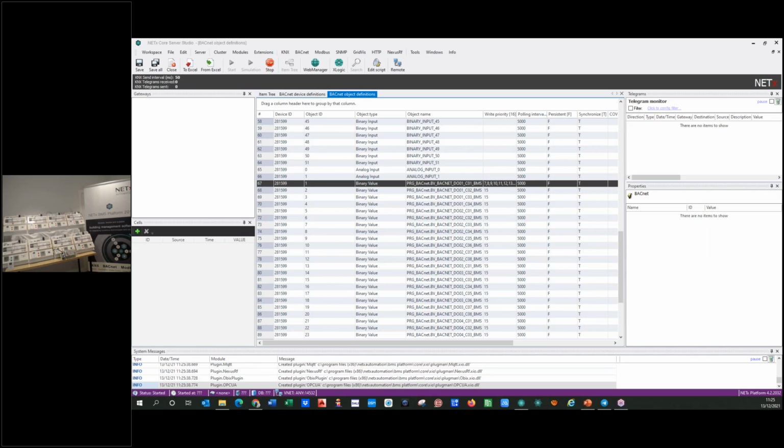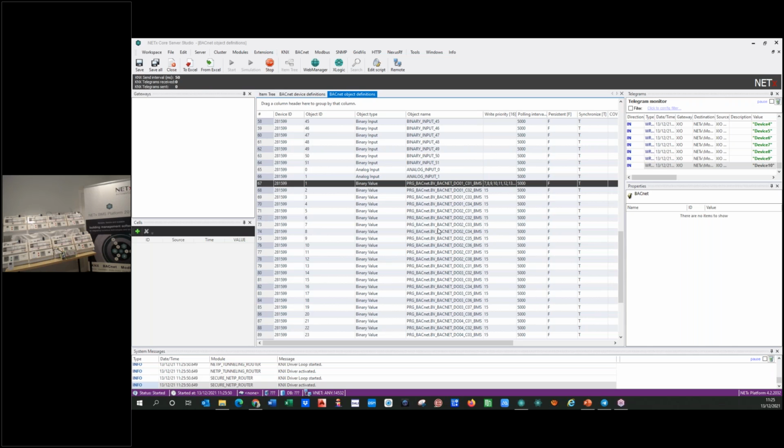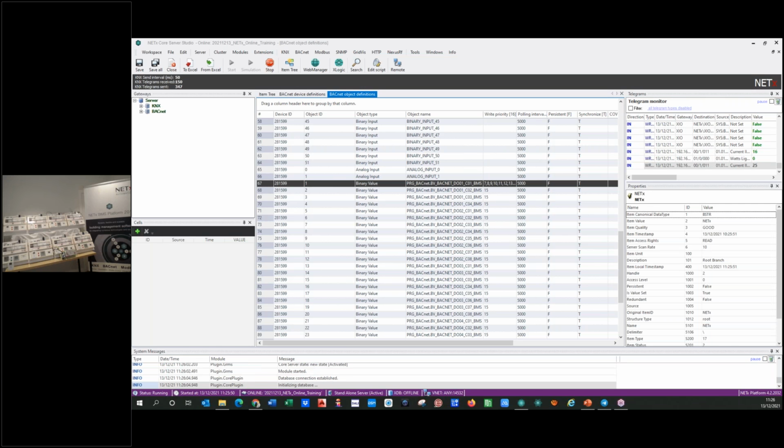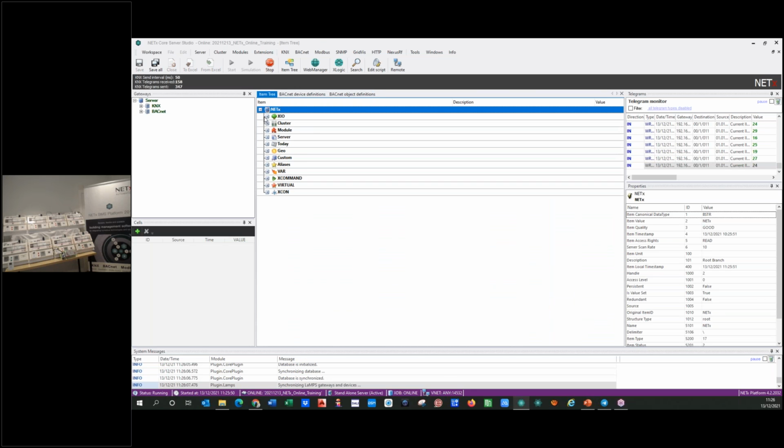the priority for writing. And this is a BACnet specific thing for the writing objects. And this is possible to do very easy here for testing, because sometimes the manufacturer for the BACnet IP device decided to put the priority for the priority. So you have to test, because it's not working fine at the beginning, but this is because of this reason. But you can test it very easy for one object, for example, and then you can get as a result